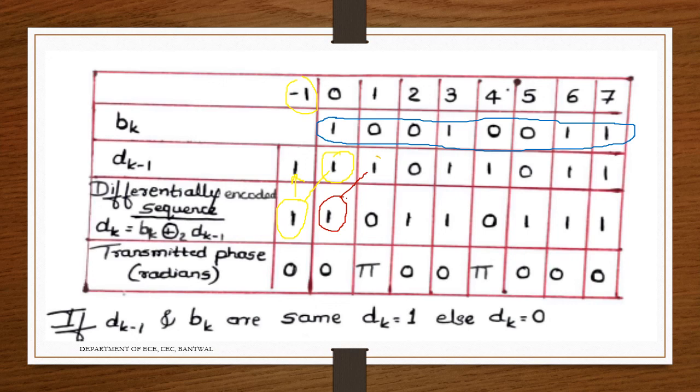That time we use DK minus 1. What will happen here? 0 and 1 will become 0, because for XNOR, dissimilar bits will not be the same, so it becomes 0. Next it is given here. The next input bit is 0, and what we shifted from DK into DK minus 1 is 0. Shift it here. For 0 and 0, similar bits, it will become 1. Shift it here like that.